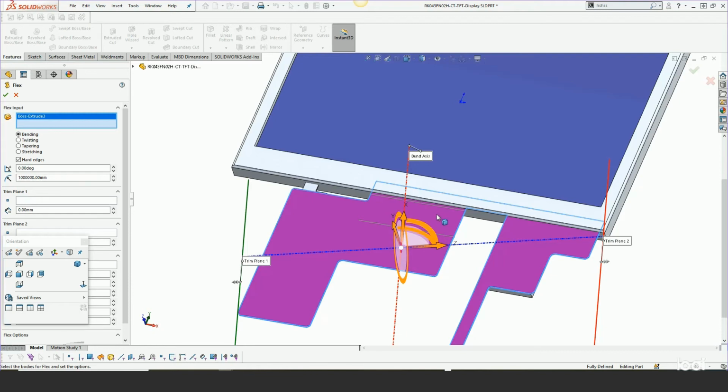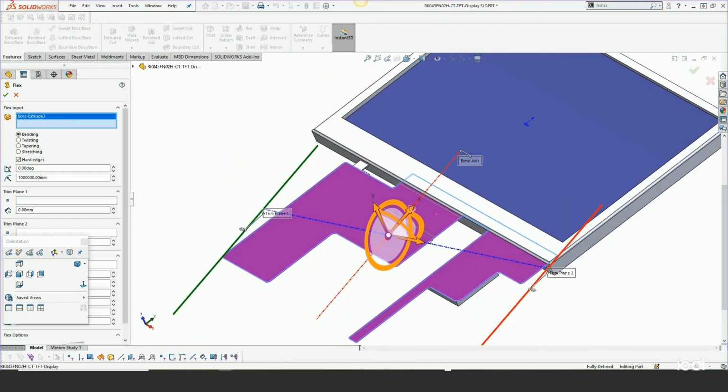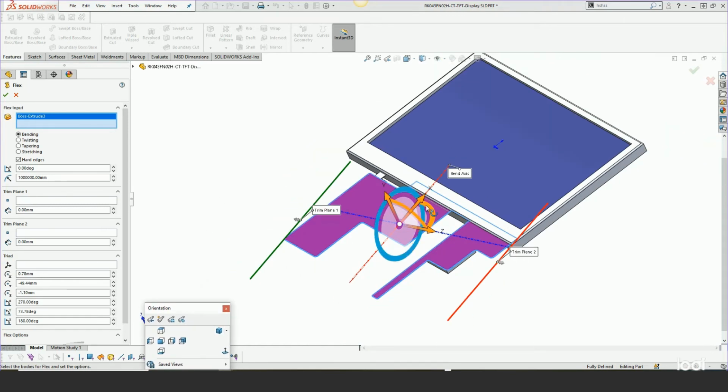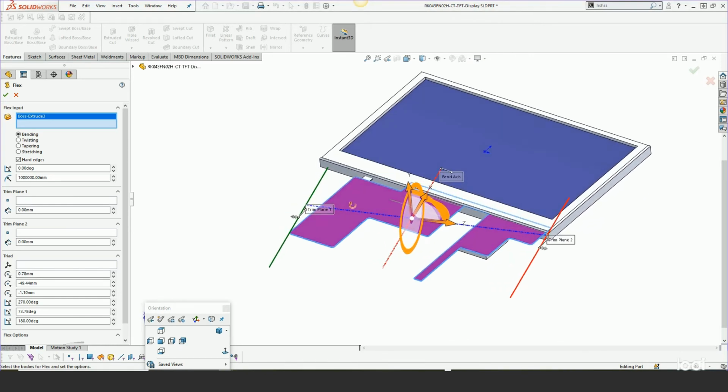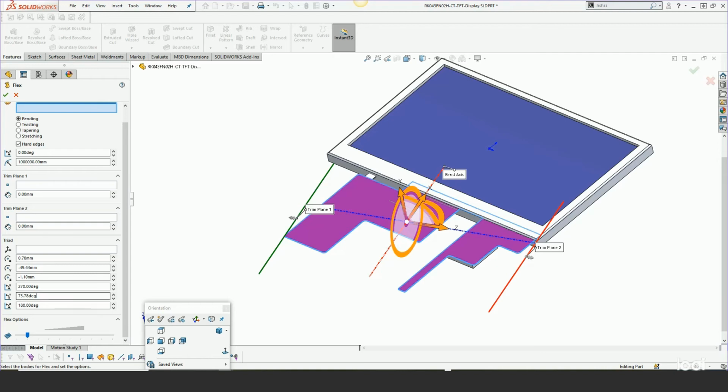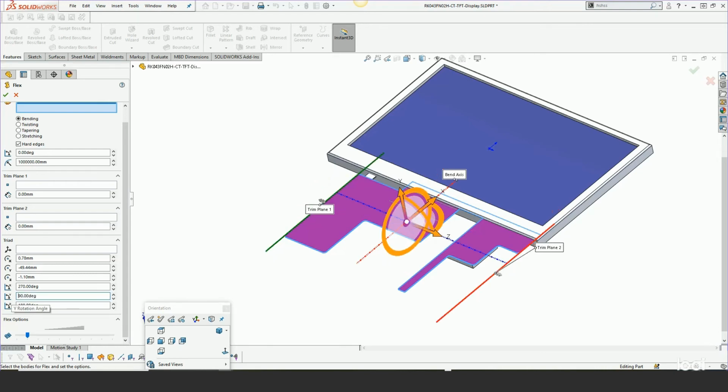So if I were to just do that and flex this, and let's go down here, this is where, remember I had said it gathers up the bounding box of the existing body that you've selected, and you can notice that it's really not oriented perpendicular to the default vectors of the origin. So if you go down into this section, you can clean that up by just taking these values and making them what they need to be.